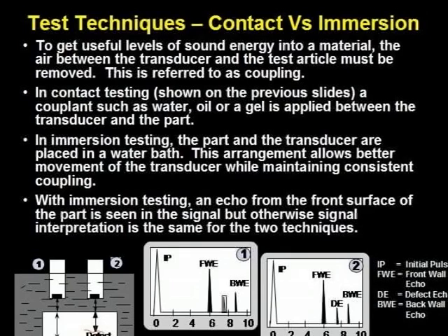Air has a very low acoustic impedance. Both the density and the velocity of sound are low for gases when compared to solids. This means that the sound generated inside the transducer will tend to stay inside the transducer. In order to get the sound into the test article, the sound generated by the transducer must be coupled to the test article using an intermediate material whose acoustic impedance permits the sound transmission. Usually a liquid is used to match the impedances of transducer and test article.